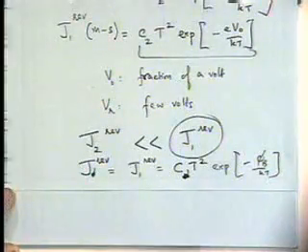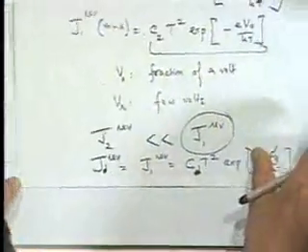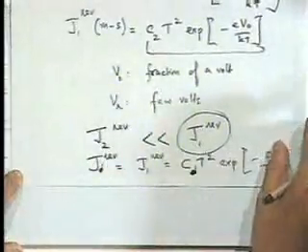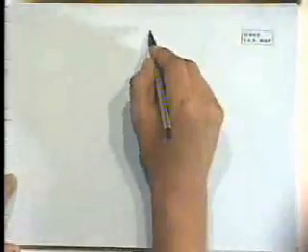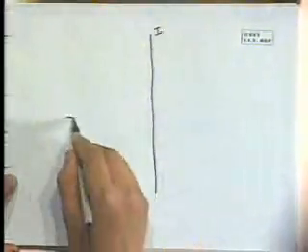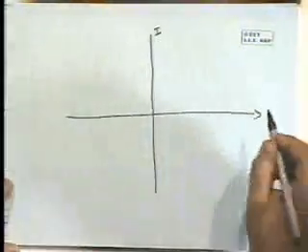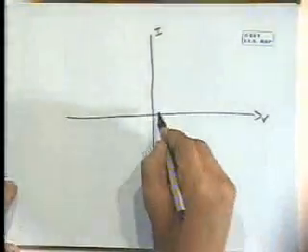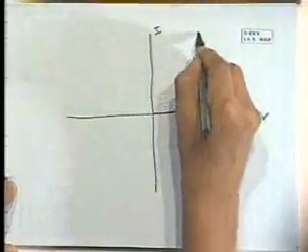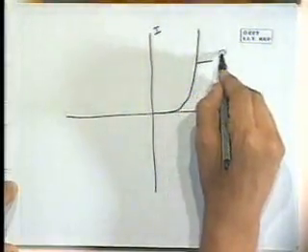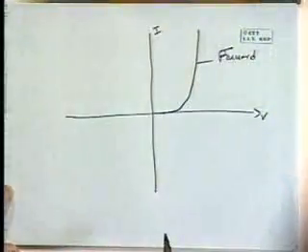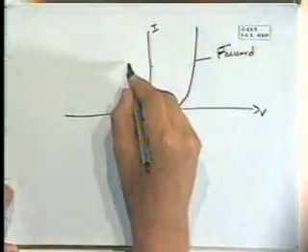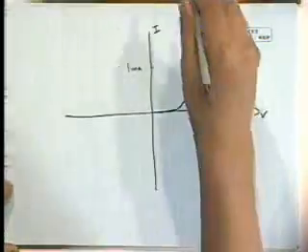All right? So now we are in a position to draw the IV characteristics for the Schottky junction for both reverse and forward. And when we do that, I'm going to draw current versus voltage instead of current density, which we obtained, simply a matter of multiplying it by A. In the forward direction, we will see some behavior like this, which has the exponential behavior, and say some milliamps or something like that current flowing.